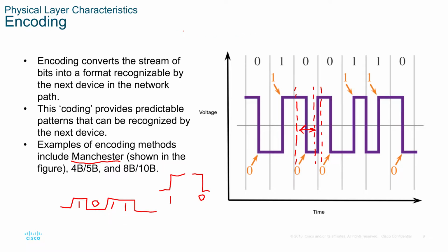Because even though one side, and just taking a rough number, one side may send out data with a 9600 baud rate, and theoretically, the other side should also be 9600. Are they exactly 9600? Probably not. Maybe this one is 9575. Maybe this is 9630.